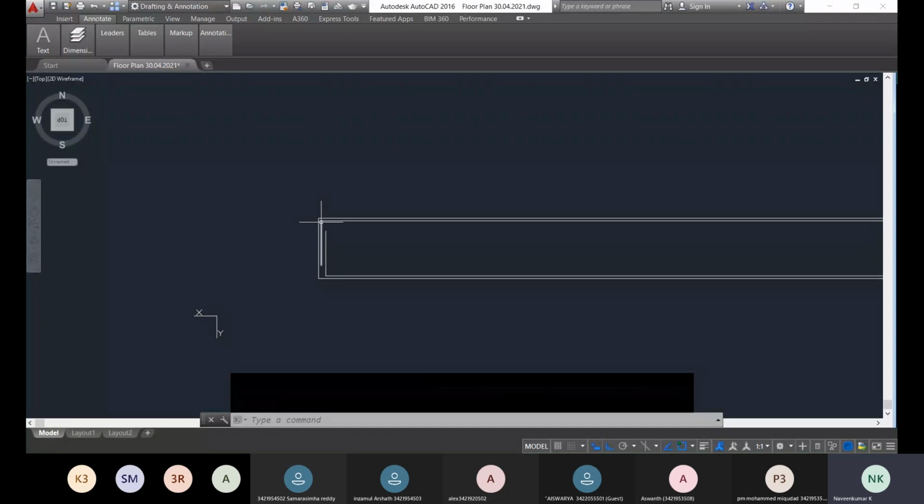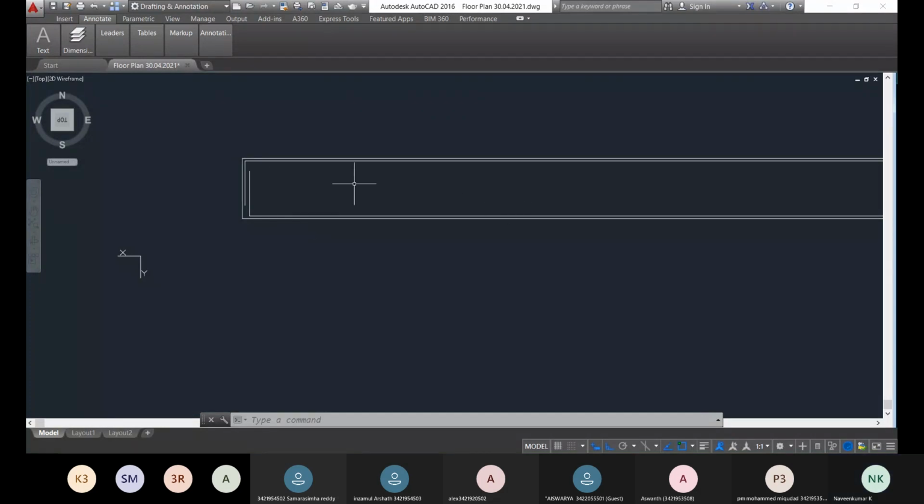Now you're going to do the distribution reinforcement detailing. So for that you should consider the shear force and bending moment condition in this particular solid slab of the bridge. Okay, so what is the shear force? It will be maximum at the corners and minimum at the centers, almost at the midpoint of the simply supported structure. So the shear force intensity is maximum at the corner and minimum at the edges. If you consider the bending moment intensity, it is vice versa of shear force. It will be minimum at the corner and maximum at the support.